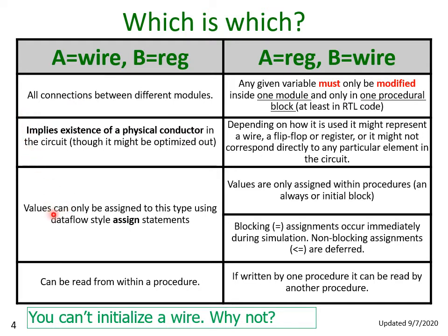One key restriction is that you can only assign values to it using assign statements, and assign statements can only be used outside of procedural blocks, so you shouldn't be using an assign statement inside an always block, for example. Now, some simulators, I think students may have discovered that QuestaSim actually permitted this, but it's really permitting something that's outside the specification of Verilog.